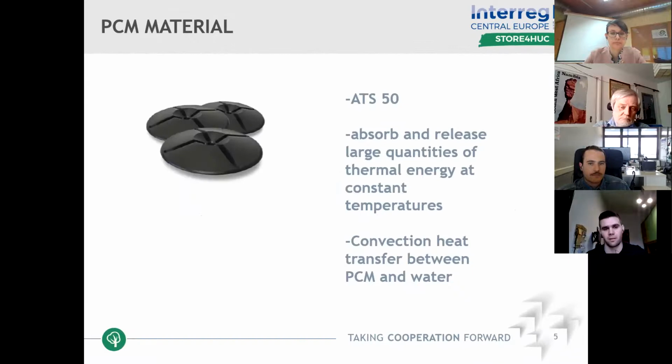As I said, in the tank, beside the water, we also have a phase change material. In this situation, we use ATS 50. It changes its phase at 50 degrees Celsius, and we modeled each layer with 2 variables of PCM material.